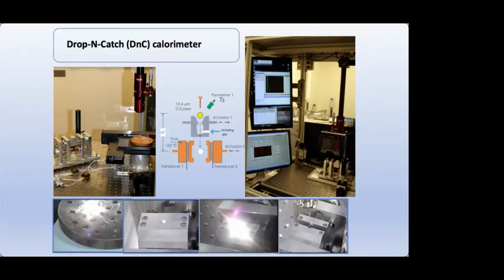We have taken this in a different direction, namely to use containerless melting, to use a levitated sample heated with a laser above a very small calorimeter, and to drop that sample into the calorimeter to measure its heat content. To do this, we need very good control of the sample geometry, the sample temperature, the calorimetric process. And indeed, we still have some issues we need to solve, particularly in terms of the temperature distribution in the sample. Nevertheless, we are now getting accurate data.